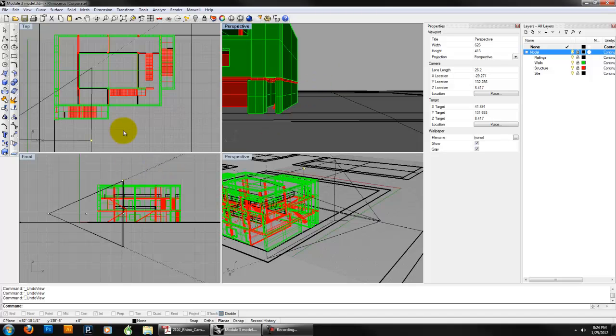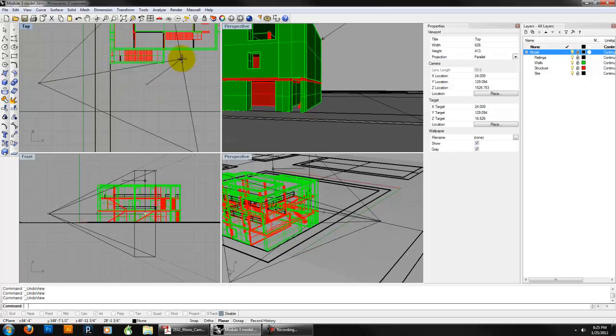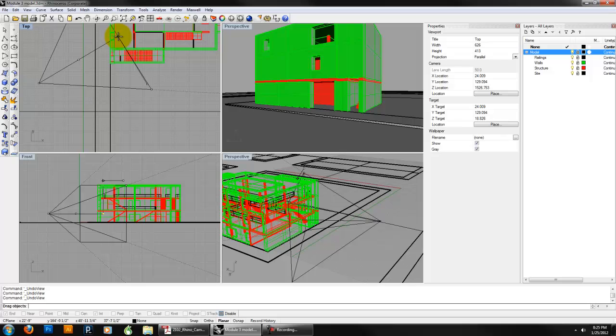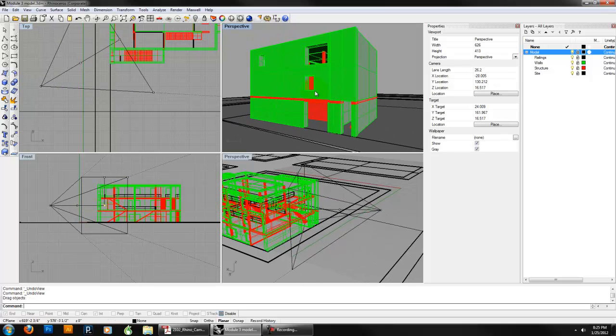When you're choosing in the top view, this is where this actually happens quite a bit. When you click on that point, look in a side view at which point you're selecting. If I choose this point, the first camera point, you can see how that one lights up in the top view. Don't do that. Select the second one, and that is going to be your target. Okay? And so then, if I'm moving that, I'm moving the target, which is what I want in almost every case. Okay? So those are the selections for a basic camera view.